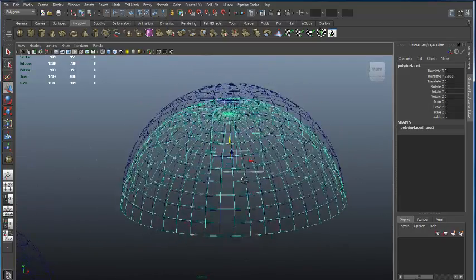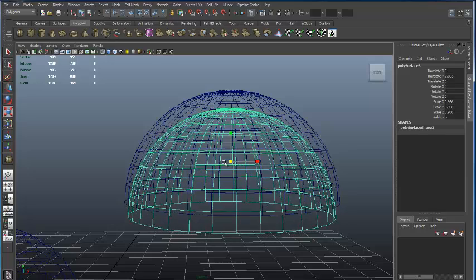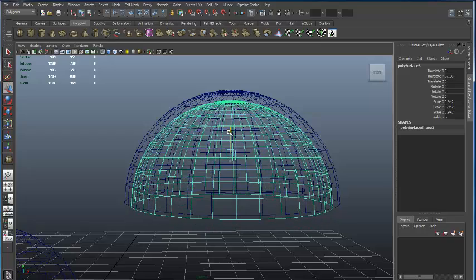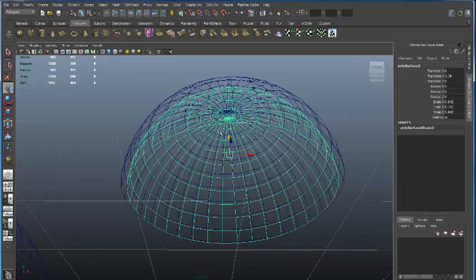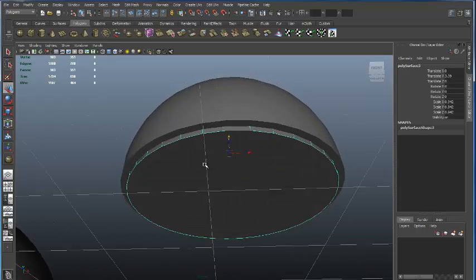However, if I look at this from a see-through view, it gets a little pinched here because all I've done is really drop the same shape inside itself and bring it back down. So what I'm going to do is scale this interior one down a little bit and maybe even just move it up a teeny bit like this. Whenever I model things, I like there to be thickness, especially on something that might be experiencing or handling a lot of force. So a rocket engine is going to be experiencing that force.